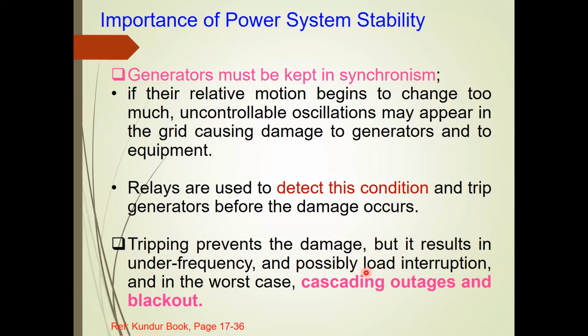So that we call load shedding. That is possible, but again, this is perhaps not desirable. The power has to be met by the consumers, and in many cases, if there is load shedding or power disruption to the consumers, some of the companies have to pay a penalty. So again, the problem arises if you have load shedding. This is again undesirable.